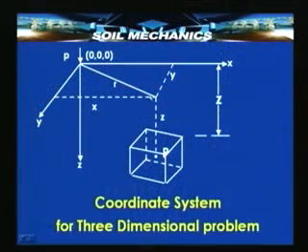Well, in order to understand the theory of elasticity, we need to have the basic definition sketch of the problem. So, this is the basic definition. There is a load capital P which is applied on the surface of the soil. The surface of the soil is defined by the xy coordinate or the plane xy. The depth is defined by a coordinate z, positive downwards, and any three dimensional element such as the one which is shown here will have coordinates at the center which will be given by x, y, z or r and z, where r is nothing but root of x square plus y square in this case.